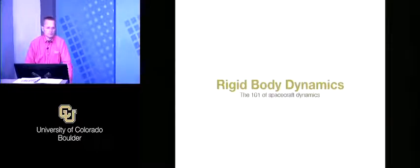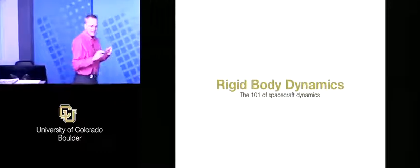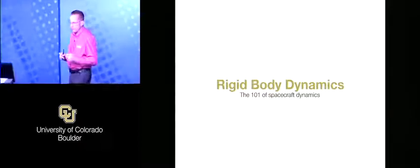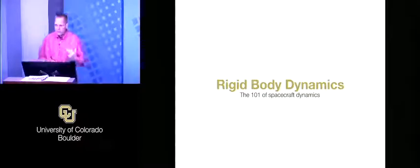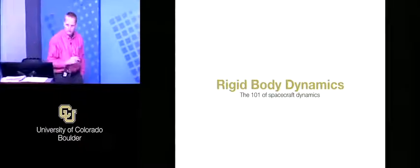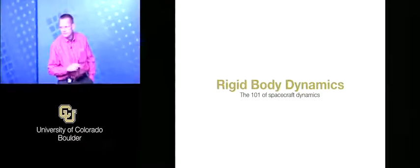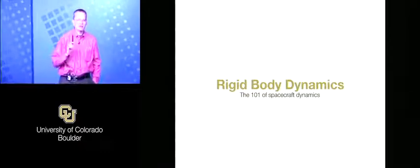That's it for continuums. Now we're freezing them. So now we're moving from a continuum blob to a rigid body. What is the key thing that changes here? Transport velocity. Be more specific. What specifically changes in these math expressions we saw? R dot becomes omega cross R. Almost. Omega cross R. There you go.